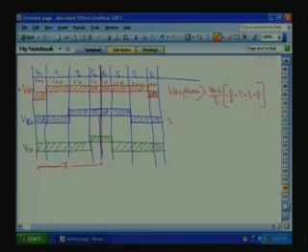Now, let us take VB0 average. Again this is equal to VDC by 2, you are taking the volt second and we are averaging. That means VDC by 2. Here also minus T0 by 2. Then minus T1, because during the T1 period it is minus T1.